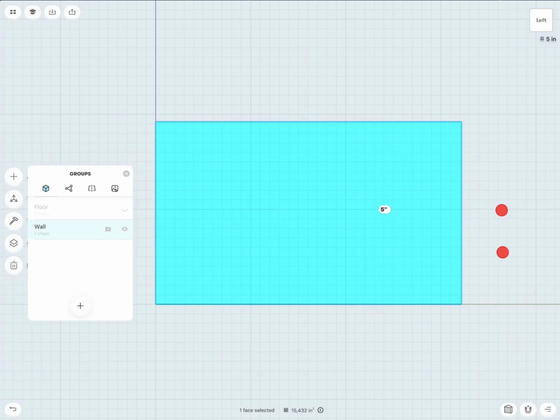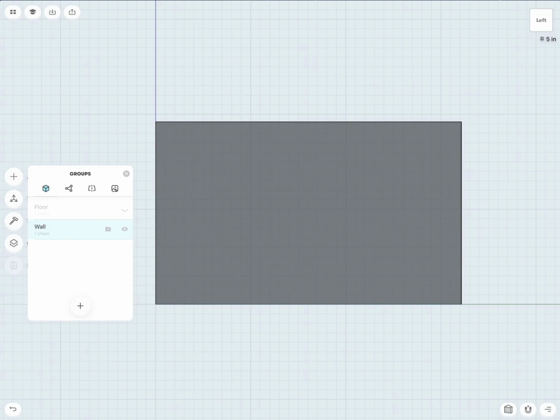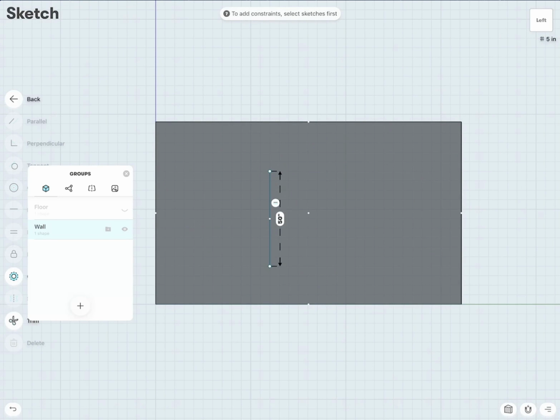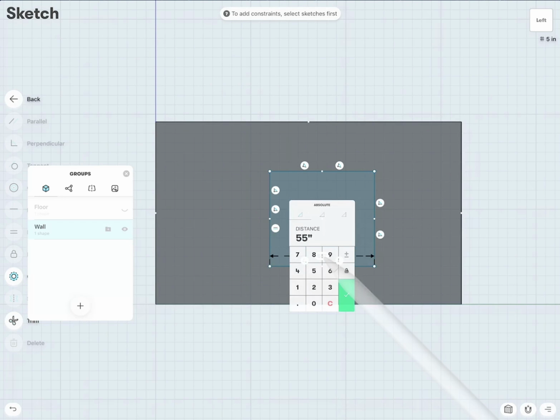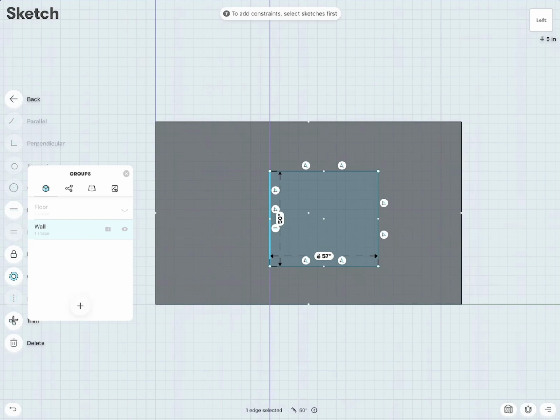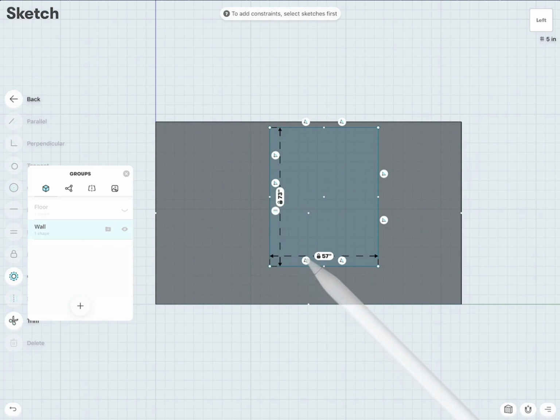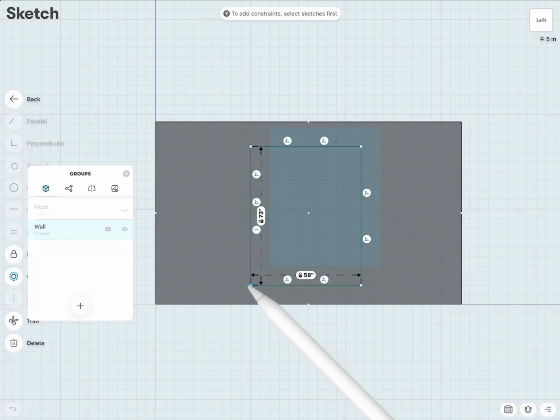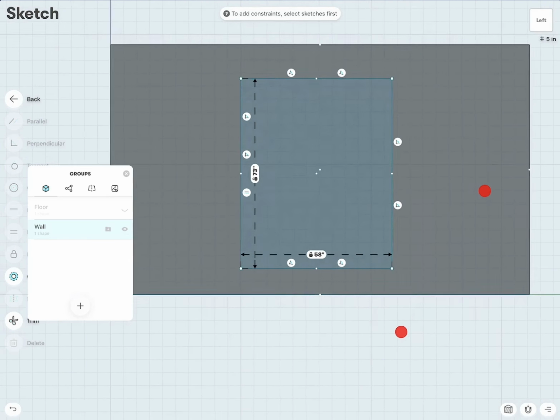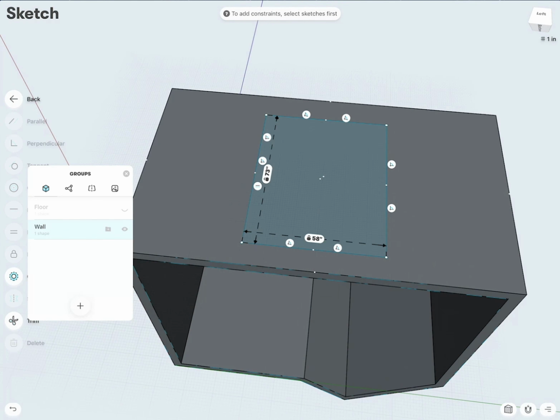So when I now start drawing a rectangle, it draws it actually on that face. So with the pencil, I can click somewhere else and then draw myself an opening. Nicely with horizontal and vertical lines. This opening should be around 50, let's say 57. I make this a little bit bigger because there's another element I would like to show later, and this one we make 73. Let's make this 58. And to specify the height where this should be and the center, you see both lines have actually a midpoint.